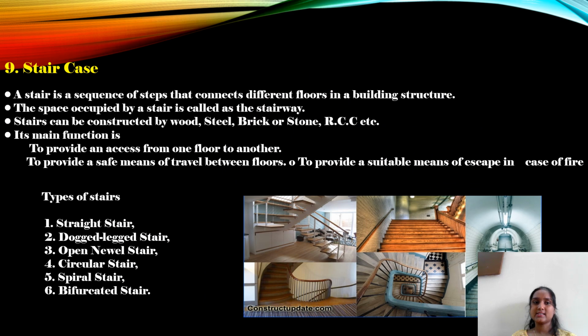Last one is staircase. A stair is a sequence of steps that connects different floors in a building structure. The space occupied by a stair is called the stairway. Stairs can be constructed by wood, steel, bricks or stone, RCC, etc. Its main function is to provide access from one floor to another, to provide a safe means of travel between floors, to provide a suitable means of escape in case of fire. Types of stairs are straight stair, dog-leg stair, open newel stair, circular stair, spiral stair, bifurcated stair.